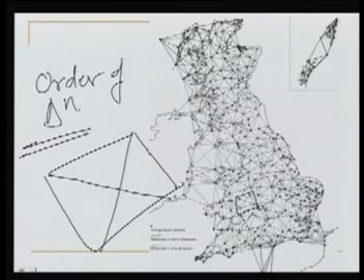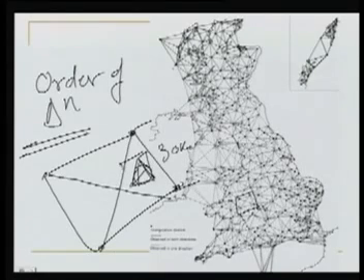Now the sides of this quadrilateral are very big, of the order of 30 kilometers, and your area of interest may be only here. So what you would do is pick up the control from this main network and extend it in this area. You will establish some more network of triangles here, which take the control from the first network available to us and then extend it in this area.